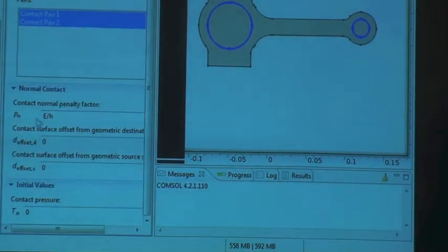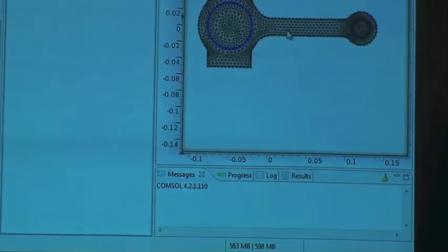And then this is the penalty factor. We also noticed that the penalty factor wouldn't converge right, and we went online. There were some issues, but they were saying that if you take the Young's modulus and divide by h, where h is the size of the mesh, it takes the smallest mesh size, because in your mesh these all have different sizes. Apparently that was a good enough parameter that it works pretty well.